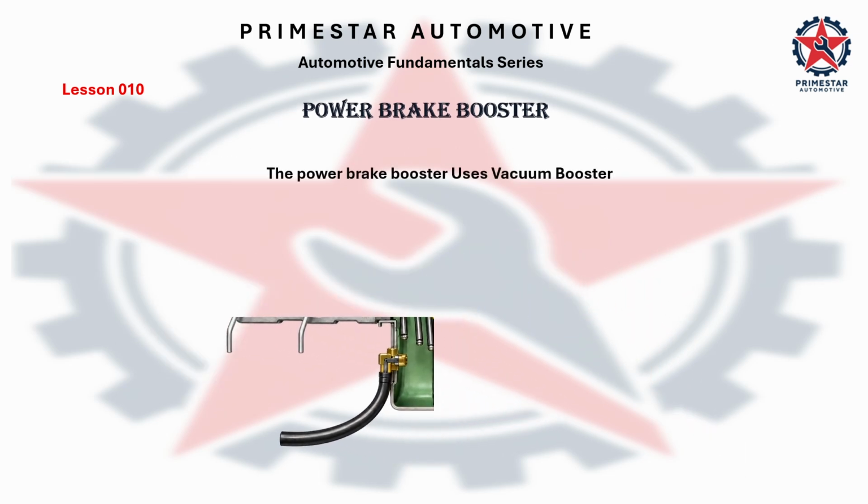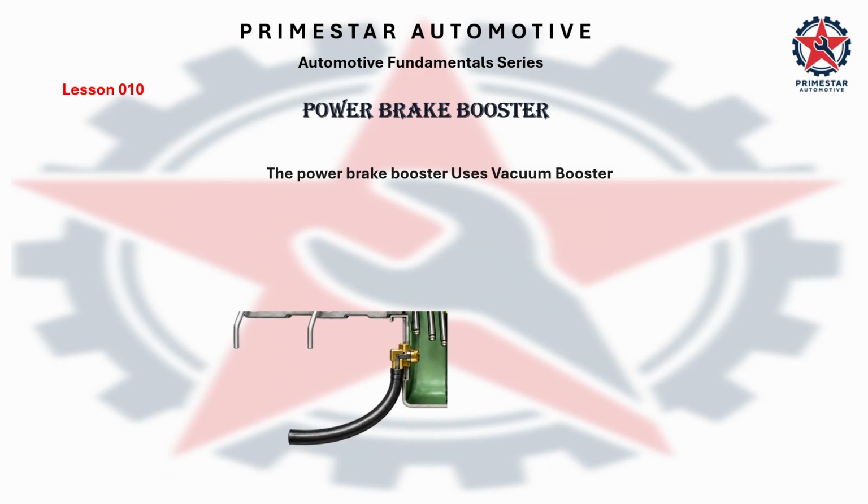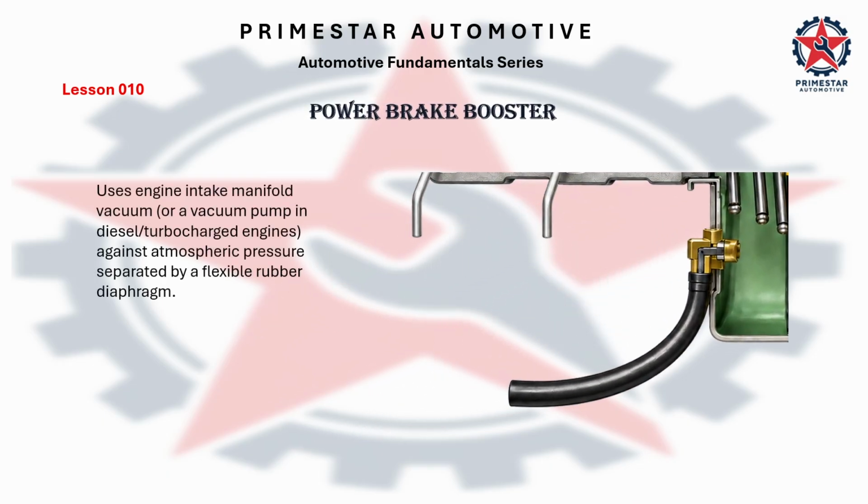The power brake booster uses vacuum. The brake booster uses engine intake manifold vacuum, or a vacuum pump in diesel or turbocharged engines, against atmospheric pressure, separated by a flexible rubber diaphragm.